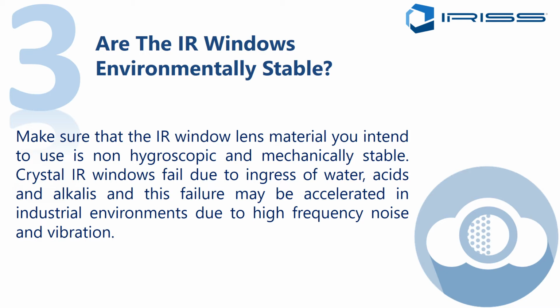So we always say that you need something that isn't going to let you down. And crystals, because of their hygroscopic and fragile nature, will change. The transmission will change. And if that transmission changes, how can you calculate the temperature? So again, we stipulate for industrial infrared windows that crystals don't really work.